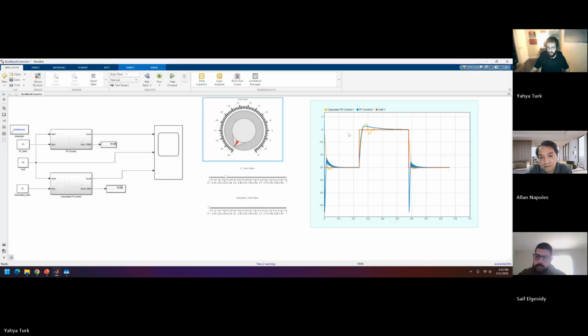Perfect. So when we do this analysis, if we did not reduce our gain for the PI, we would have significant voltage ripples. Reducing the gain gets rid of the voltage ripples, but causes aggressive overshoot, and it significantly increases the settling time. For the PI, we have some instability, but once we adjust the gain, we end up with a pretty ideal system.